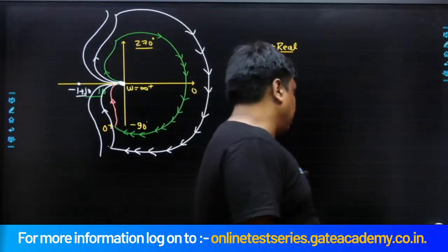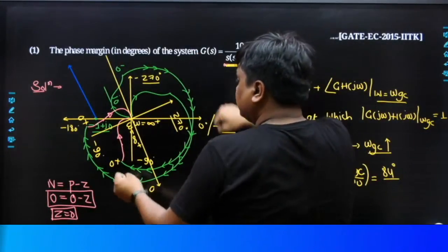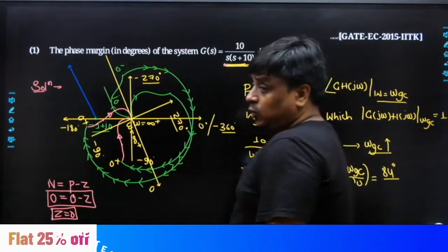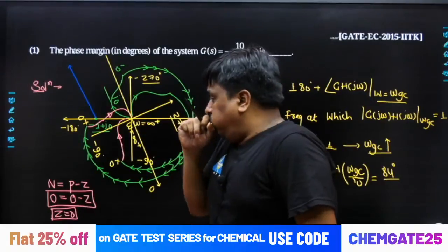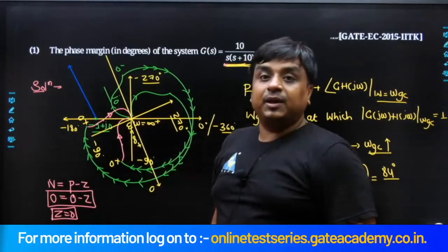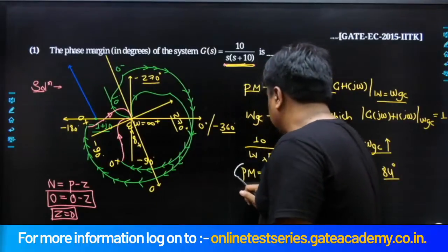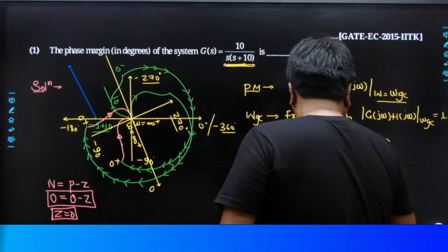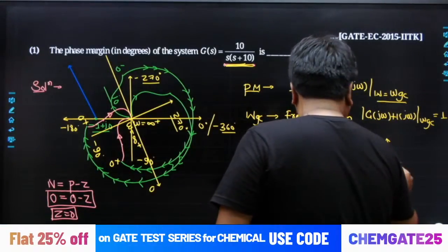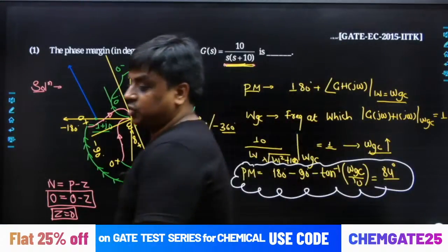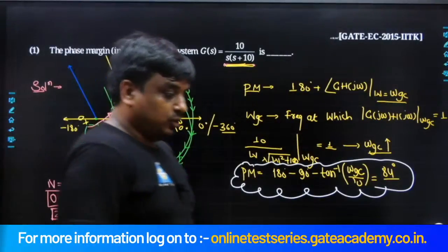So as far as this problem is concerned, when we dislocate the complete plot in the clockwise direction, because we are offering the lagging in the system, after certain lag the system becomes an unstable system. How much lag we can provide to that system is nothing but the phase margin. This much margin in phase we have. We can derive where this formula was deduced, but I think for the crash course it is not required. In the full course, definitely I would be talking about those things also.